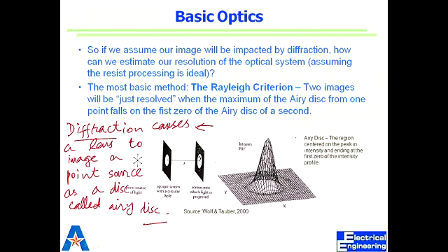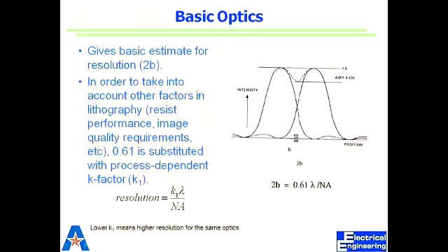A point source comes out as a disk, a region of high intensity with rings around it. So pitch becomes an issue, because how close you can make two features becomes a problem due to the interference in between. You can't discriminate between those two, and that degrades resolution. So it's not just the feature size, it's the pitch also. How often can we repeat this?